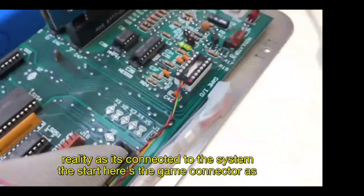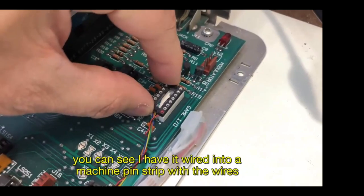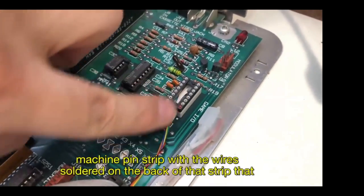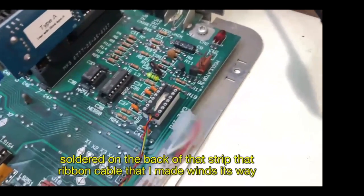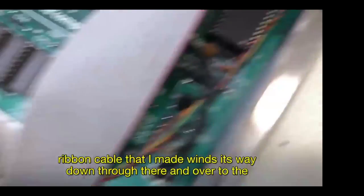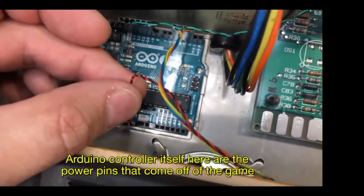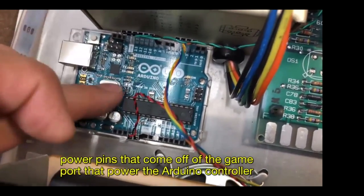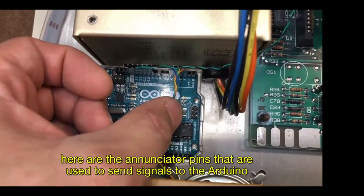To start, here's the game connector. As you can see, I have it wired into a machine pin strip with the wires soldered on the back of that strip. That ribbon cable that I made winds its way down through there and over to the Arduino controller itself. Here are the power pins that come off of the Gameport that power the Arduino controller. Here are the annunciator pins that are used to send signals to the Arduino.